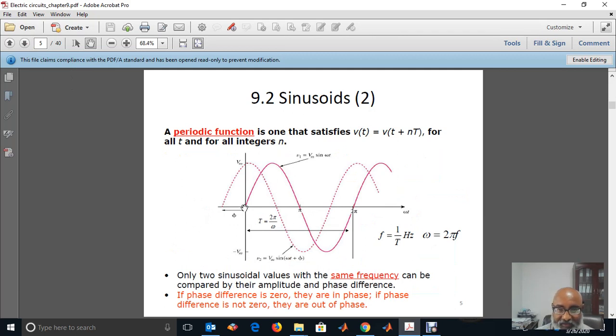So this is again the previous function, v(t) equals Vm sine omega t. This is the maximum, Vm. It starts from 0 and goes up, crosses pi, comes back at 2 pi, and this will repeat. This plot is as a function of omega times t, which is an angle.